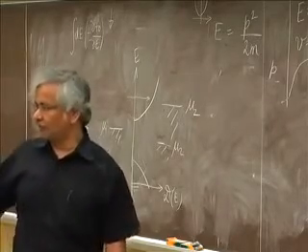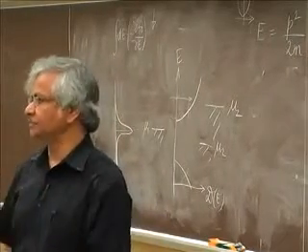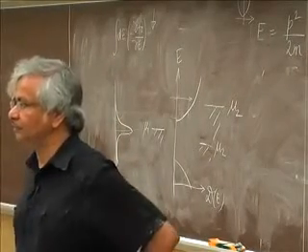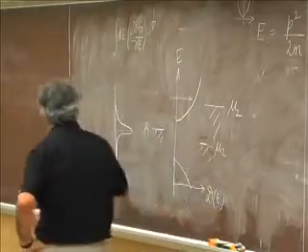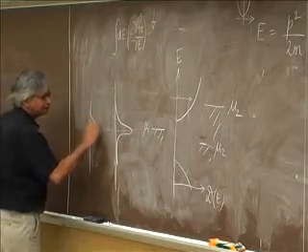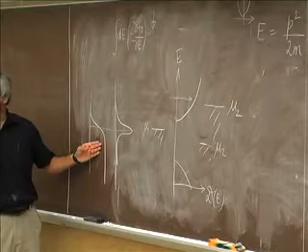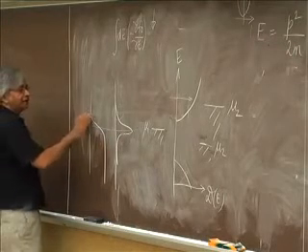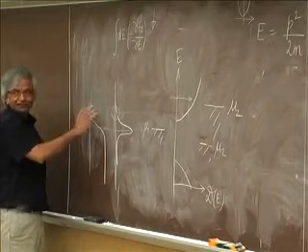And of course, then all the conduction is happening on the tail of that function. This is the non-degenerate limit that Mark talked about. A lot of the calculations in semiconductor texts are usually in this limit. Because in this limit, you see the Fermi function looks like this. And of course, down here, these two things don't look at all similar. But up here, those two functions are essentially just a constant times each other.